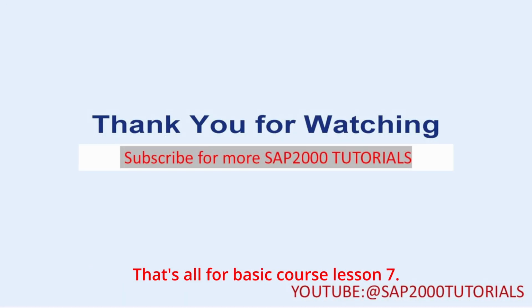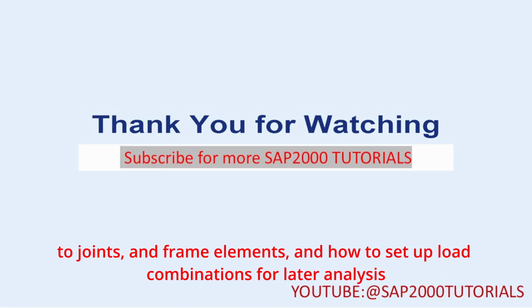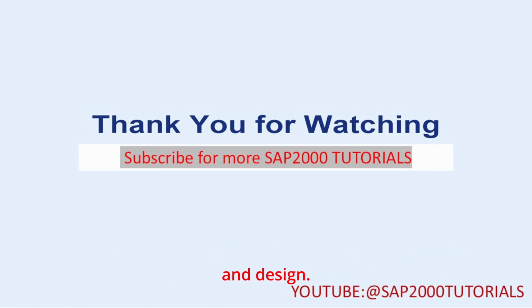That's all for Basic Course Lesson 7. In this lesson, we learned how to define different load patterns, how to apply loads to joints and frame elements, and how to set up load combinations for later analysis and design.